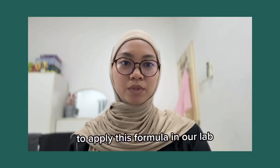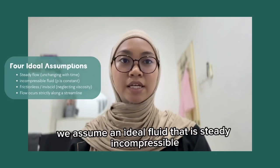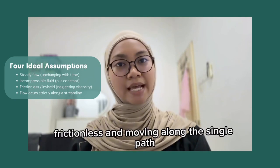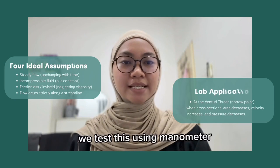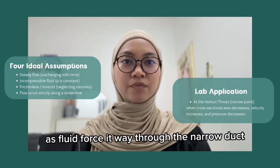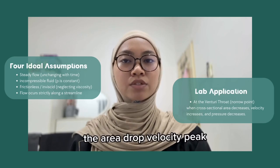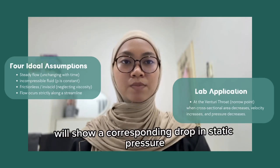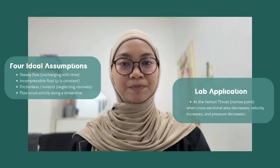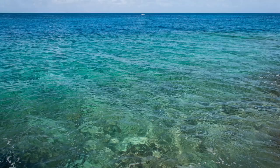To apply this formula in our lab, we assume an ideal fluid that is steady, incompressible, frictionless, and moving along a single path. We test this using a venturi meter as fluid forces its way through the narrow throat. The area drops, velocity peaks, and our manometer tube will show a corresponding drop in static pressure. This is the exact relationship our lab data aim to verify.